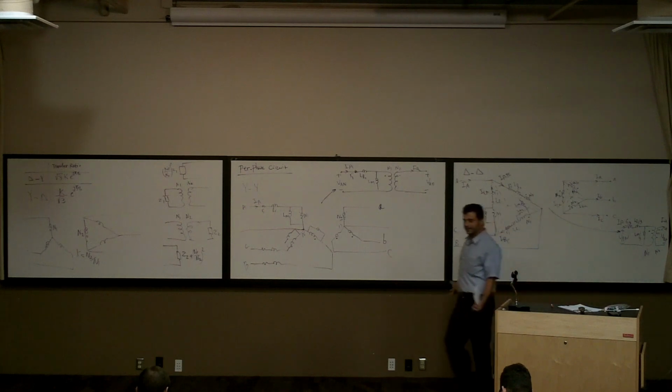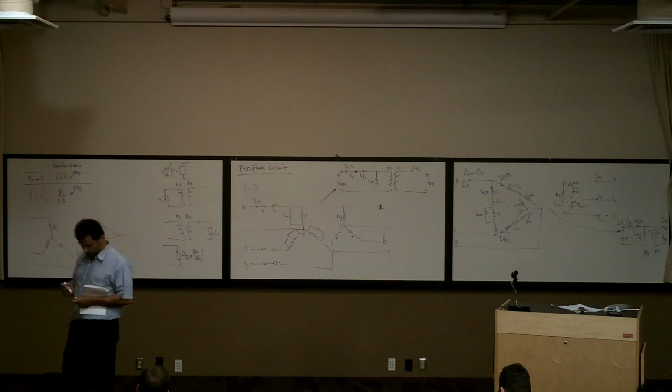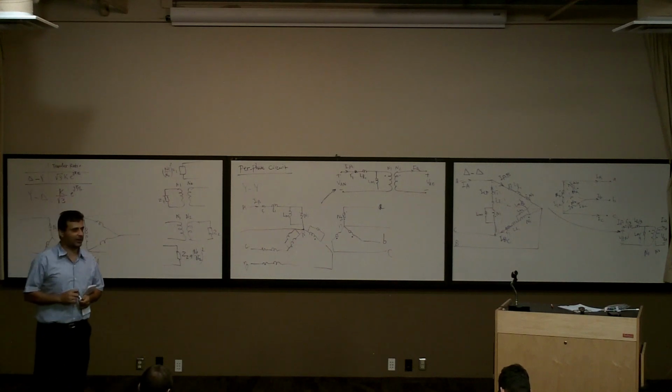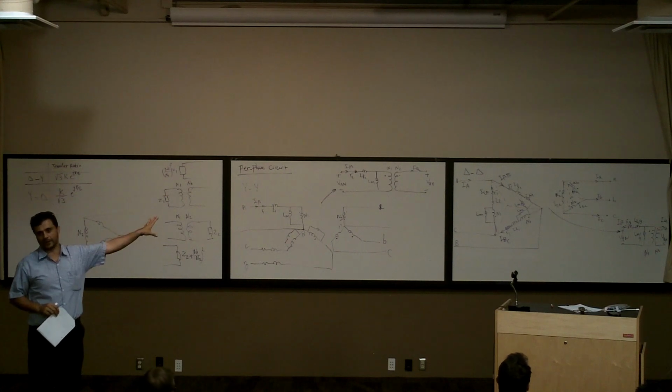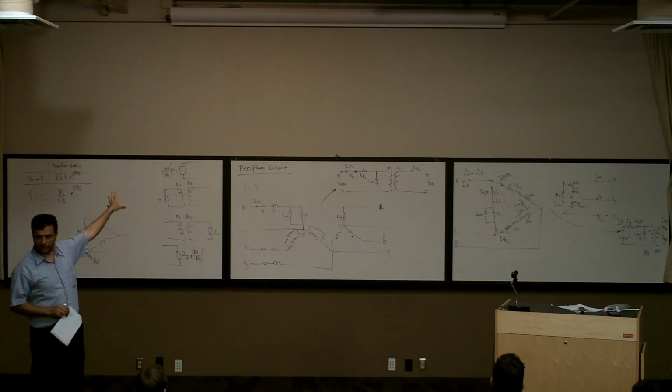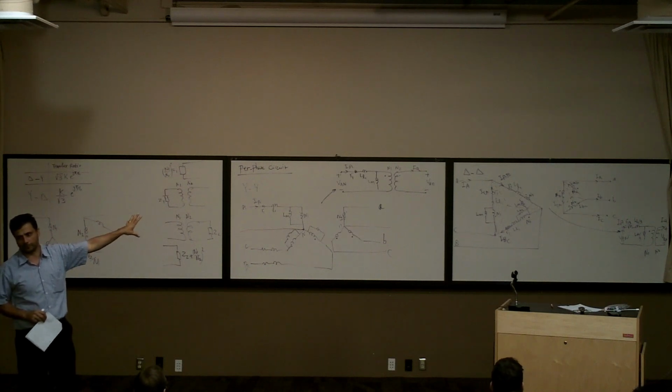So again, it's like a single phase transformer, exactly what we have for a single phase transformer. The only thing is R and L are going to be divided by 3. When you draw the single phase system, R and L get divided by 3, because it was a delta, we converted to the star, and we came up with the per phase circuit. Clear?